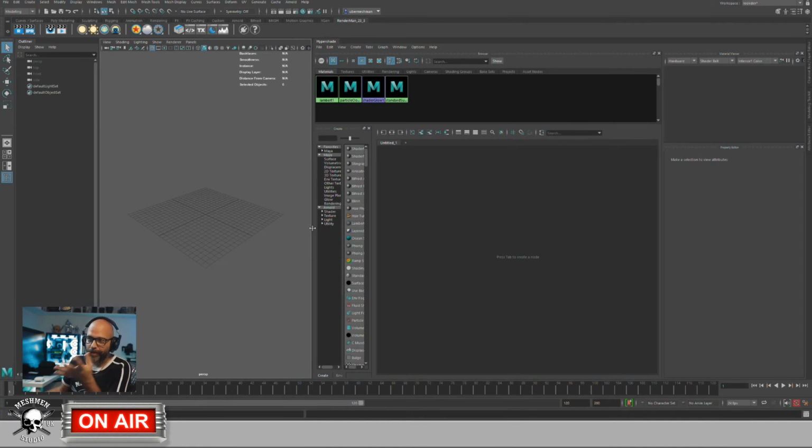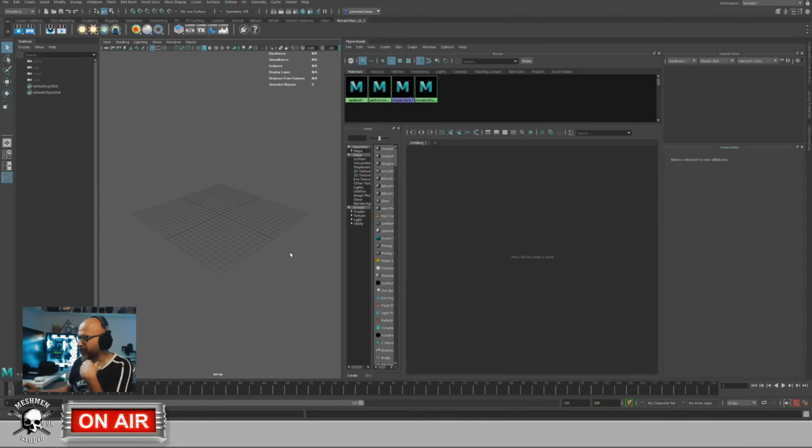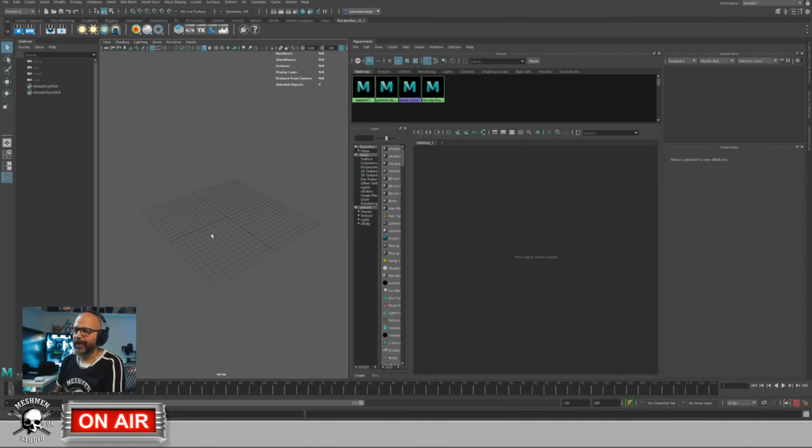So if you have a white environment and you have a specular and you start to render, you will see that if you add one specular or two specular, all of a sudden you can have more energy coming out from the shader than coming in. And this is something that the Renderman Llama shader that's going to come up in Renderman 24 hopefully will handle. From what I've heard from the tech demos, it looked like the Llama system will handle this more behind the scenes. I guess Arnold handled this better in the shader, and Renderman is not really designed to handle this by default. So let's take a look here.